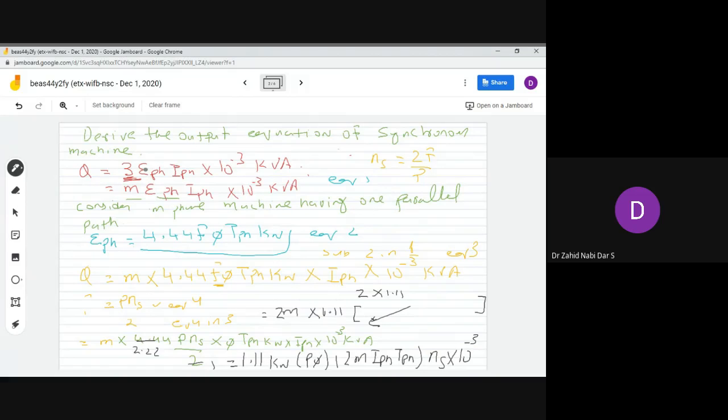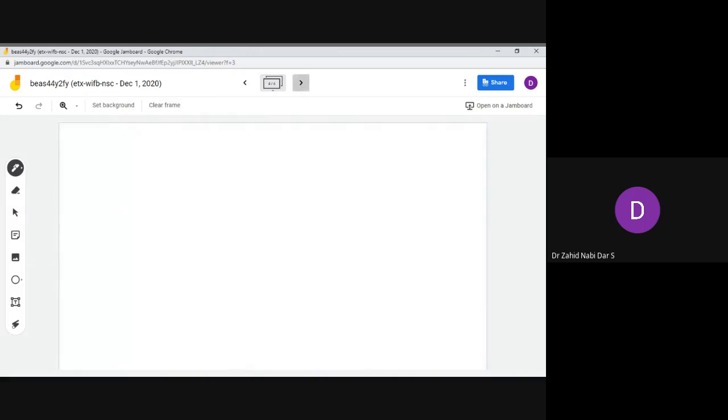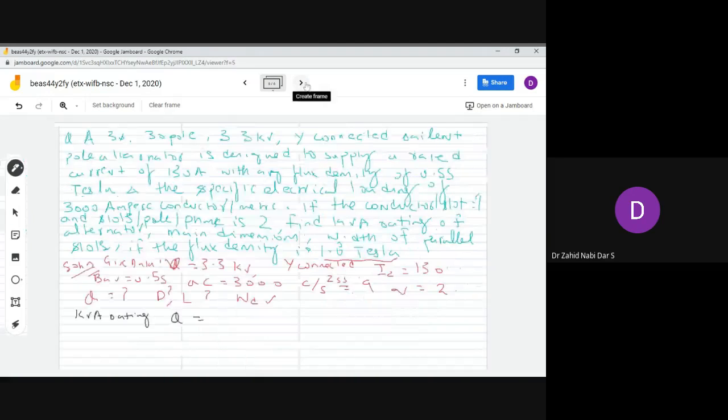Here it's a three phase machine, so already they have mentioned the value, and you can directly substitute the values. So the kVA rating here would be direct multiplication. The 3.3 kV is given for Y connected, so that already incorporates the three phase.